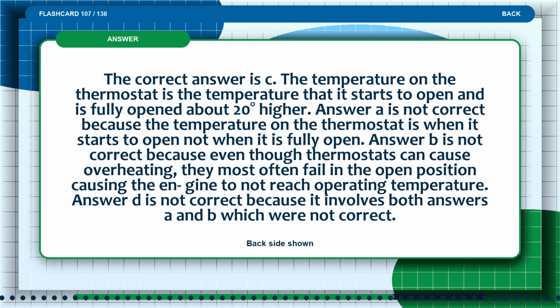Answer A is not correct because the temperature on the thermostat is when it starts to open, not when it is fully open. Answer B is not correct because even though thermostats can cause overheating, they most often fail in the open position, causing the engine to not reach operating temperature. Answer D is not correct because it involves both answers A and B, which were not correct.